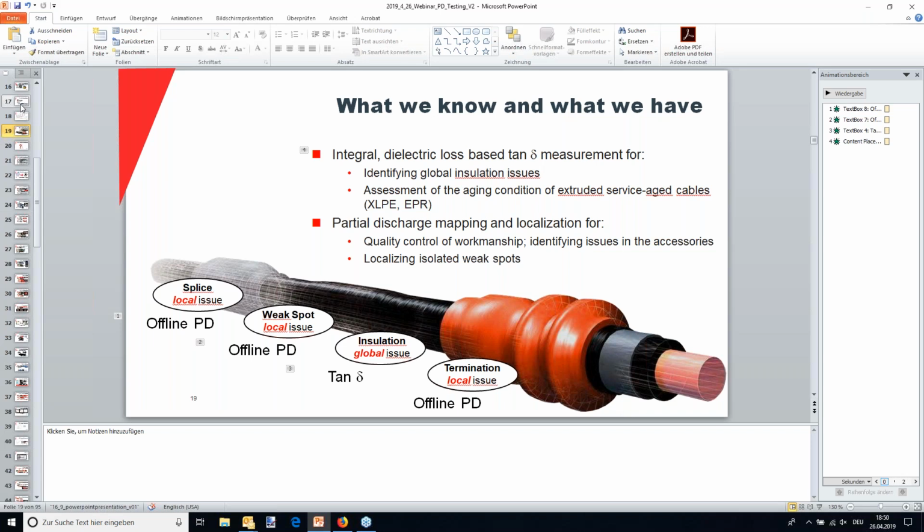So what you can pretty much say is online versus offline. Online is a tool for substation monitoring mainly, to monitor concentrated assets under system operating conditions: vibration levels, voltage levels, all these things under operating conditions, but you cannot vary the system voltage.